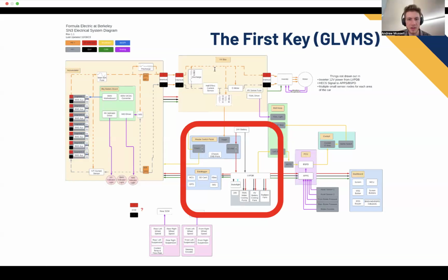All right, I see a question in the chat. The master switch is just the key for low voltage. Yes, that is correct. So it's basically just shorting this red arrow before, that goes straight to the 24-volt battery, to the red arrow after. It's either just open, and then you twist the key and it shorts. When you twist it and it's shorted, the key doesn't come out anymore, but it is removable in the off position, and that is a part of the rules.